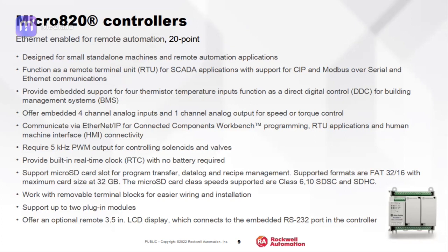We can use it for building management systems, and it is designed with 4 embedded analog inputs. So flow or temperature kind of analog inputs we can connect to the controller. It supports 5 kilohertz pulse width modulation, for controlling solenoid valves or heating applications. A built-in RTC is available for time-based functions, if we want to run some pump or application. Yes, it is built in.